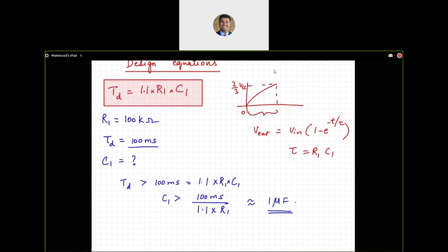And we have seen that the fake switch at least was getting debounced. Then we applied that to a counter to trigger it. When we applied that to a realistic scenario, we saw that 1 microfarad wasn't enough and we had to actually increase it a little bit. So we went to 2 microfarad and then everything was good. So that's what we did in the last class.